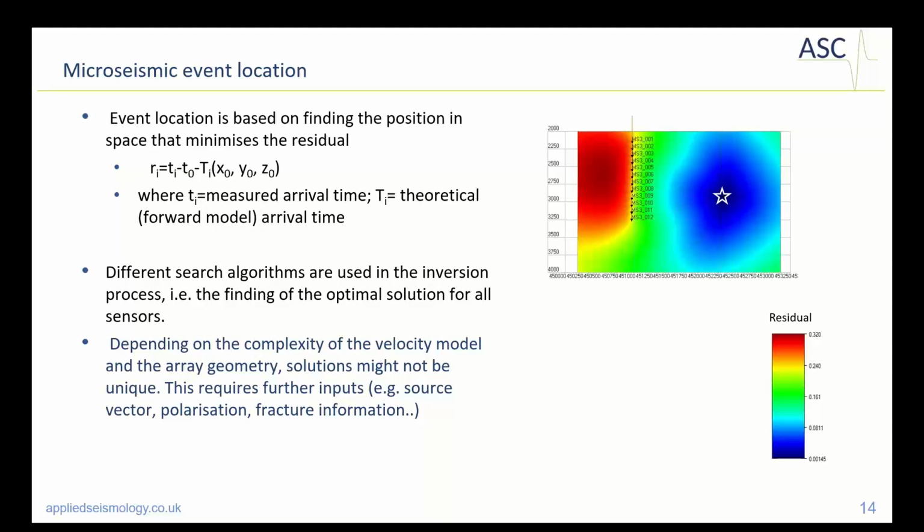It's accumulated amplitude. There was a previous question as well about calibration of the sensors in order to get source parameters. Well, that's not something that is done automatically. It's something that needs to be done on an experiment when you are working with your sensors, calibrating your sensors. You will need to have a known source, for example, a vibration table, something like that.